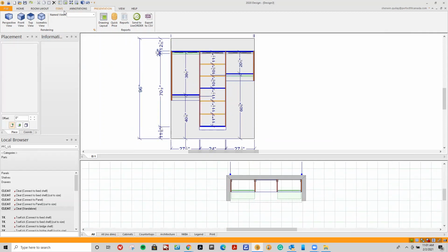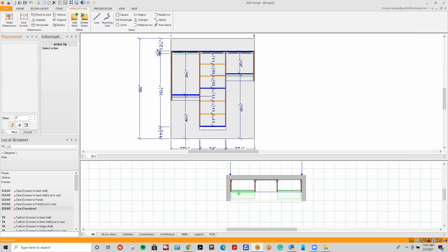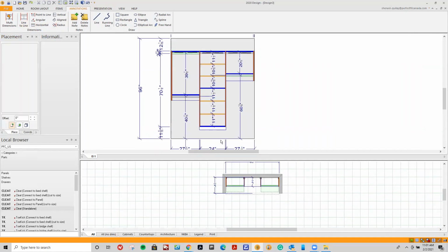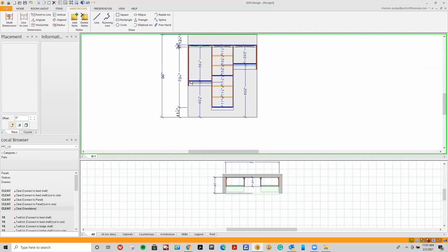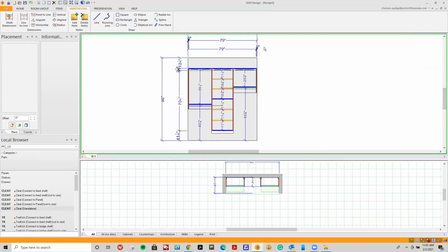Go to my top view, click on my annotations, line to line, depth 14 inches, and the depth for my walls, like so. Right click, auto dim, hide, right click, auto dim, hide. And there's just a few more. Perfect. Now I'm going to click on my line-to-line annotations. I need, oh, sorry, my apologies. There's one more here that I have to delete, auto dim and hide.